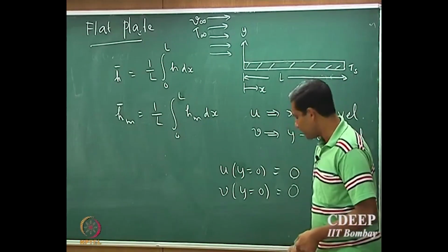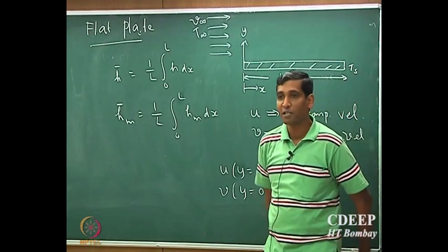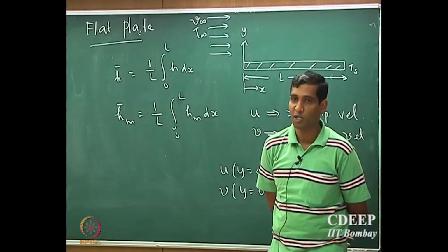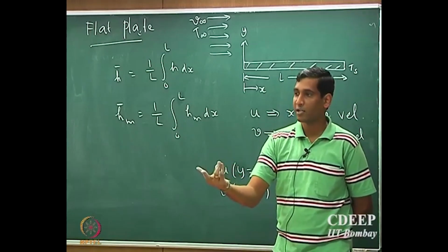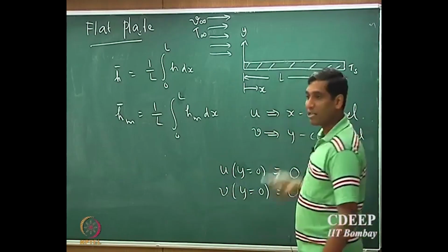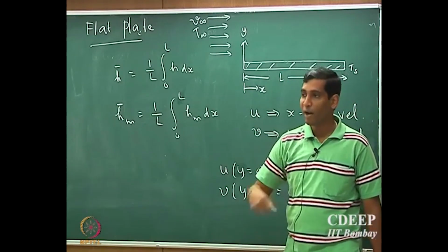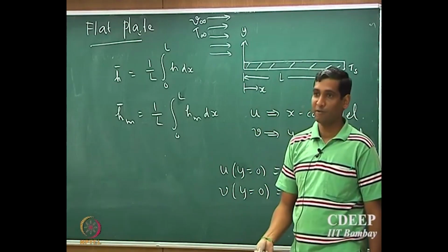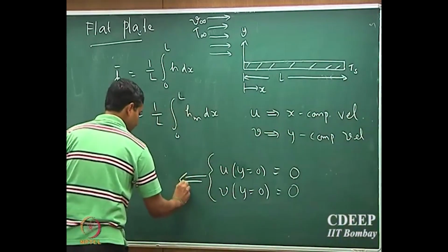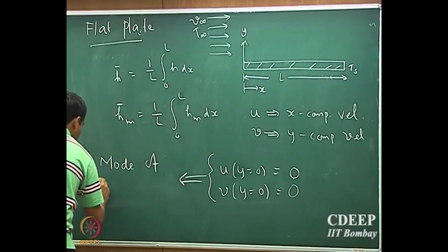So that has an important implication in heat and mass transport. What is the mechanism of heat transport at the boundary? What is the mode of heat transport? We said there are 3 modes, right? Conduction, convection and radiation, right? Because the velocity is 0 at the interface, the actual mode of heat transport from one phase to another is actually conduction.